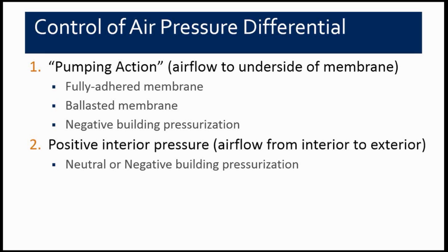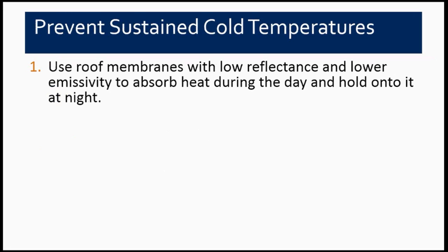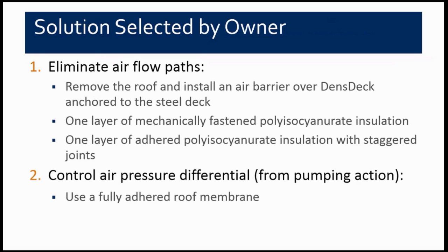A balanced membrane was considered, but as with a lot of these big boxes, they sharpened their pencils, and there's no reserve capacity in these systems. They are engineered down to the last bit of steel that they can reduce. A fully adhered membrane is a very good solution, and it requires taking out the whole membrane. We also looked into going with low reflective membranes. In the end, going with high absorptive membranes, low reflection, that was not chosen.